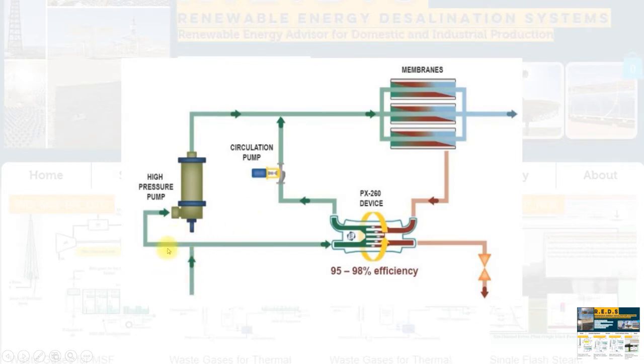We are going to use a splitter unit to split part of the feed, and such feed is going to use the pressure from the brine loss to be boosted again and go to the mixer unit, which can reduce the specific power consumption by one third compared against the basic module.